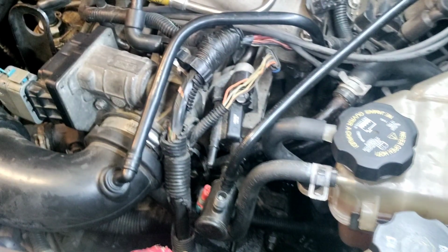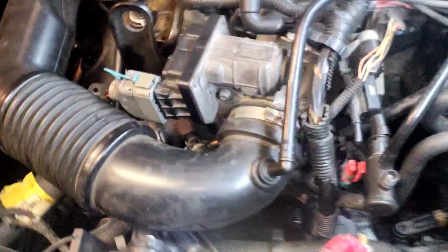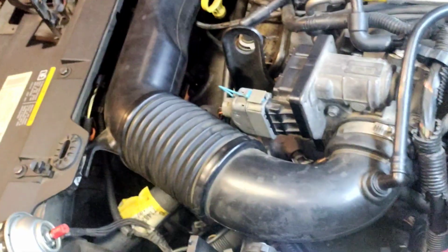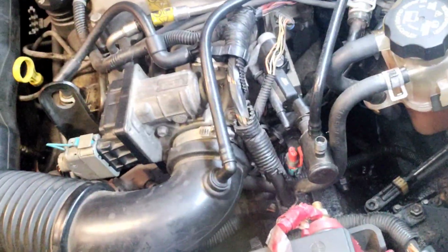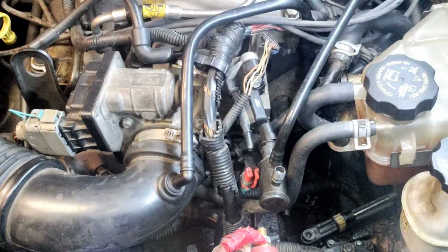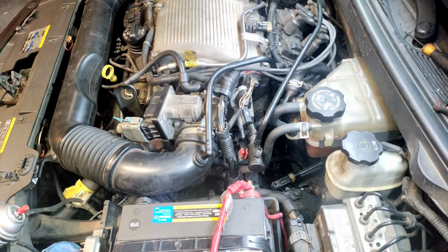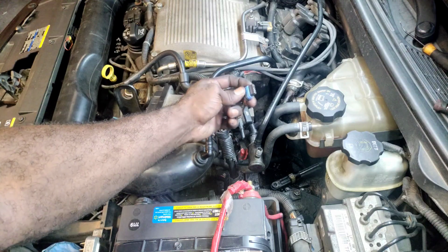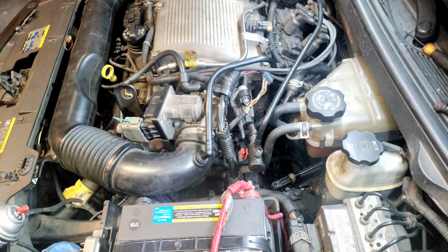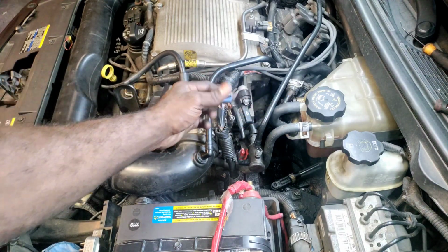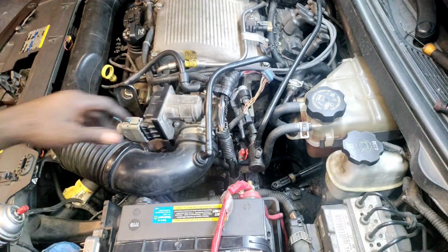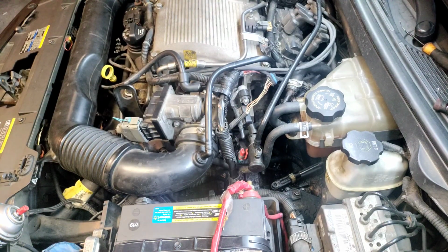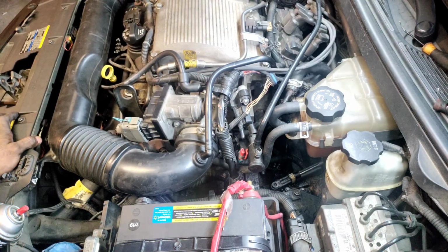All right, cool. Awesome. So next thing I gotta do is just worry about putting the aftermarket stuff that he got on there. Since the EGR valve is damaged, he got an EGR tube, so I'm gonna put that on there. Hopefully I don't have to replace that harness. Even though the connector's at the top here, I can flip it upside down, it'll still work like it's supposed to. So we'll see what happened, and then I wouldn't have to change the harness. This is fine. I'd just rather leave what's not broke on there and put something aftermarket and universal on there.